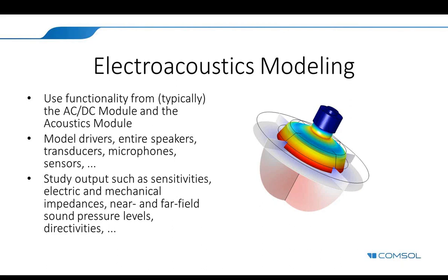In the image, you're looking at a so-called tonpilz, which is a piezoelectric transducer. You can get all sorts of relevant results, of course, from your model. Some entities that are of interest in loudspeakers include electric and mechanical impedances, as well as near and far field sound pressure levels, directivities, and so forth.